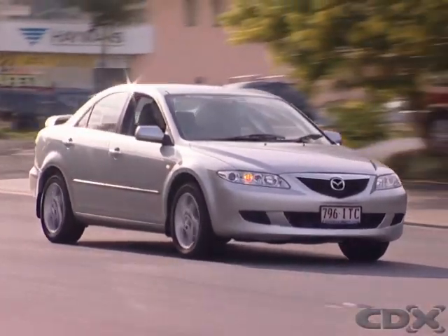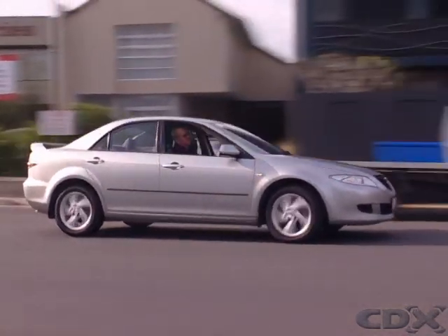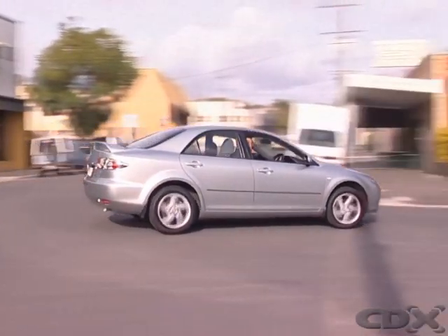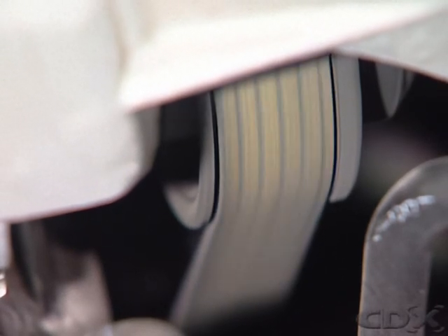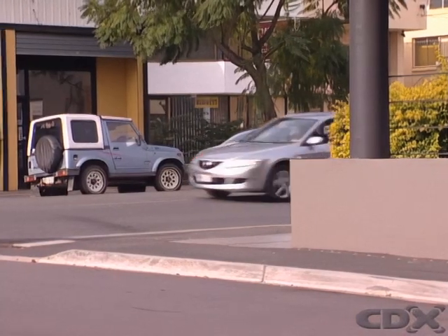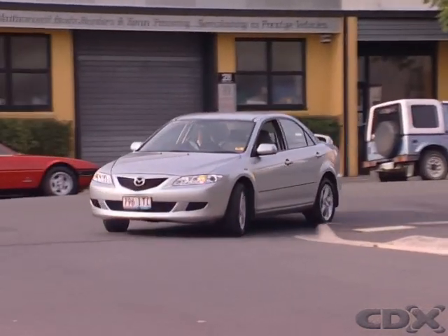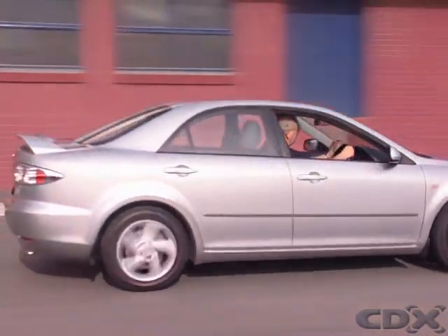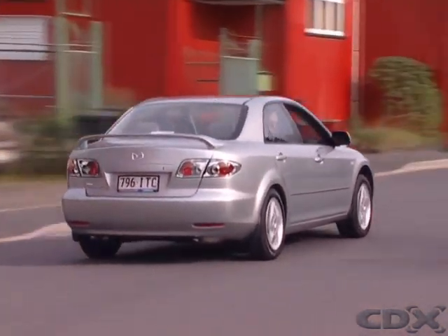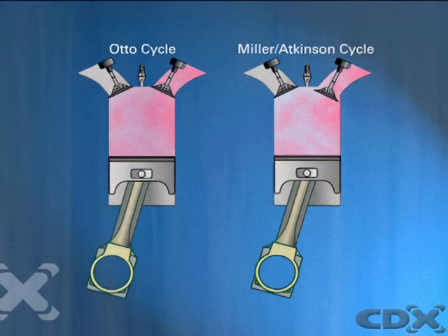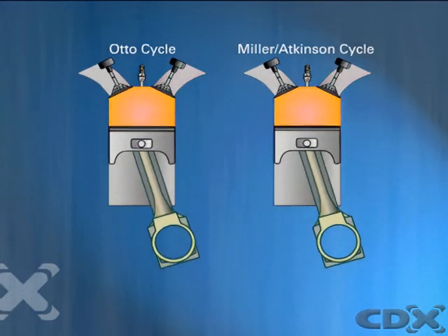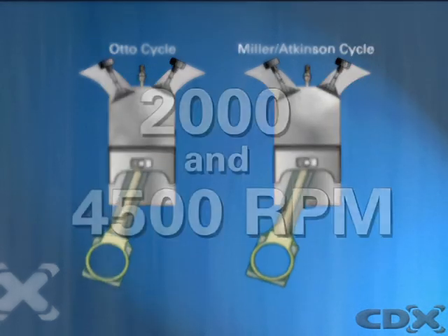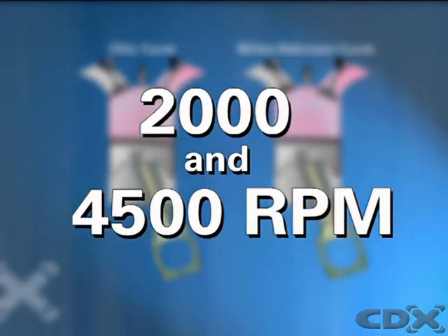When the engine is operating at low load and speed, the compressor is not needed. A clutch disengages the drive, so there's no unnecessary drag on the engine. When extra power is required, the clutch is engaged and the compressor boosts the amount of air drawn into the engine, supercharging the cylinder.